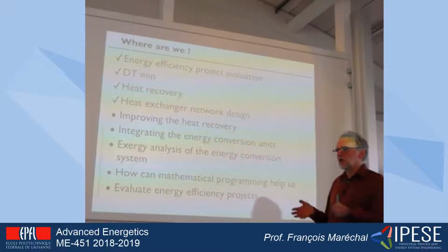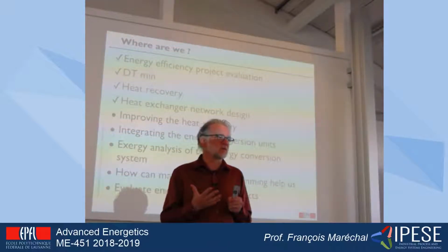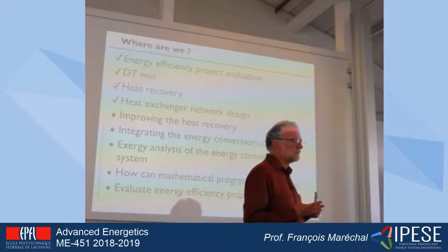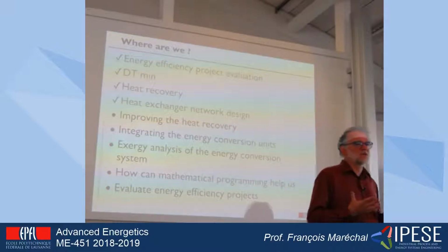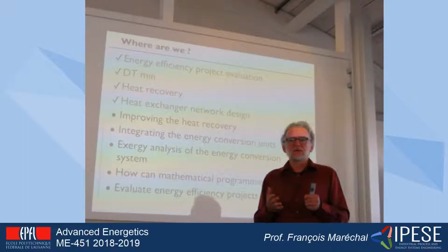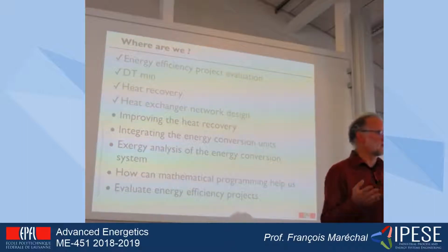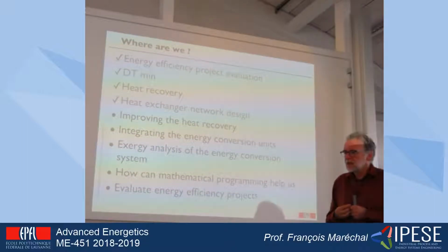From there, we were able to identify the penalizing heat exchangers, so the heat exchangers that should be modified, that are creating a penalty, the penalty being the difference between the maximum heat recovery, and therefore the minimum heat needed, and the present energy bill.